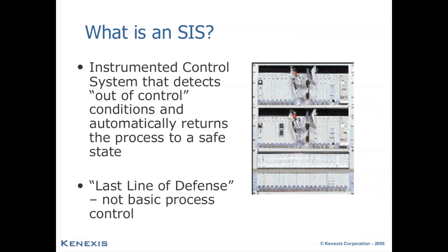Really, to obtain a good understanding of what a safety instrumented system is, we have to work within some standard definitions. The ISA standard does provide definitions of safety instrumented systems. A more practical alternative is a system that detects out of control process conditions and, importantly, automatically returns the process to a safe state. It can do those actions without intervention of an operator. It is the last line of defense or near last line of defense.